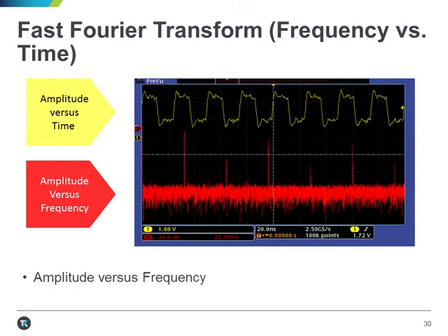Second, you'll definitely want to use cursors on the FFT display. Most scopes support this. Third and lastly, you'll try to find out how and what memory the FFT will operate on. Ideally, the FFT should use the full memory of the oscilloscope to get the best frequency resolution. Performing FFT only on the display memory makes the display update quickly, but you lose frequency resolution.